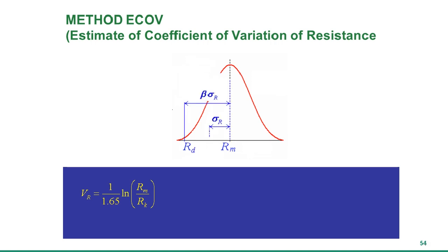And from that, we can estimate, using the reliability indexes as defined in Eurocode 0, the basis of the Eurocodes, and we can make assumptions. As I said, we can calculate the design strength. The advantage of this approach is that you can consider different betas, if it is an existing structure or a new structure, if for some reason you can justify lower reliability indexes for particular structures.